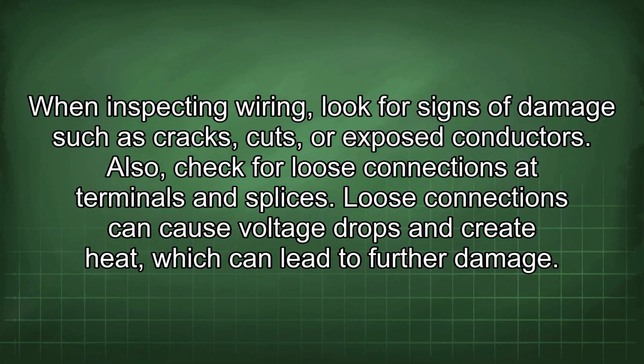When inspecting wiring, look for signs of damage such as cracks, cuts, or exposed conductors. Also, check for loose connections at terminals and splices. Loose connections can cause voltage drops and create heat, which can lead to further damage.